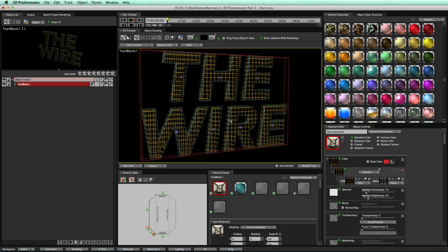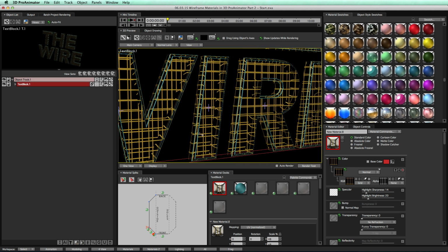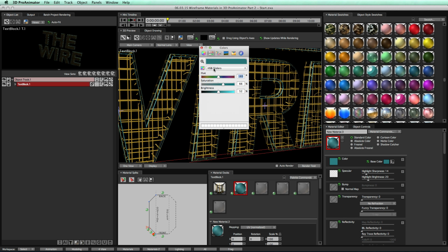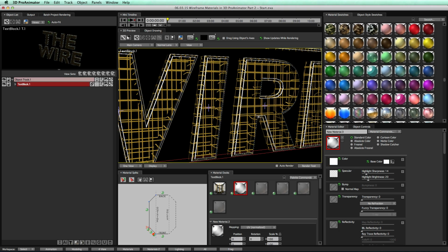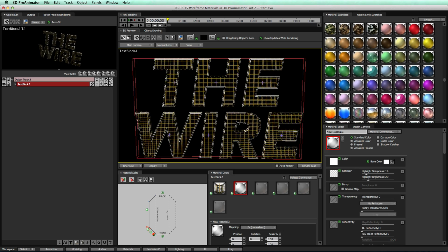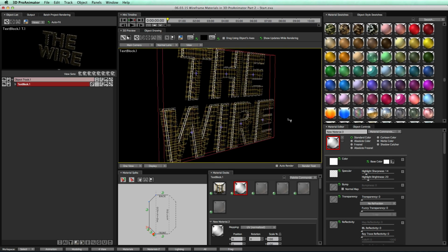So now when we zoom into our object, we can see that we have this cool gold material on the front, and we have this blue material going around the sides. And that's the other cool part about this, is that the material outlining the edges of our object does not have to be the same color. So what I can do is double click on this blue and open up this base color and then change it around. So I can have just maybe a straight white color. Let's make that straight white, and it gives us a really cool outline, and it actually makes it a lot easier to read when I zoom back here. Look at that, much easier to read now.